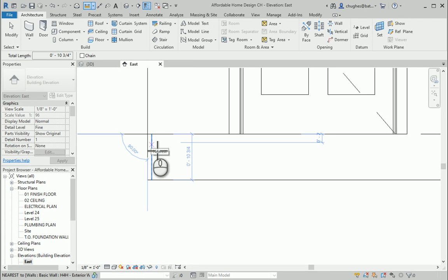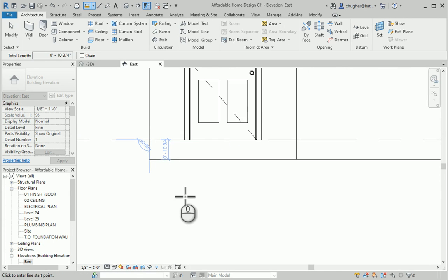Now I need to take into consideration one element that we're going to put in here, known as a sill plate. The sill plate is going to sit below the flooring, and that plate is what is used to fasten the flooring to the foundation wall. That can be done in a variety of ways, through anchor bolts, through straps, whatever that may be, but we're going to take that into account. This framing member is usually a 2x6 softwood pine framing member, and we're going to frame it.